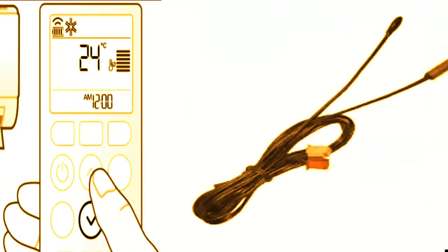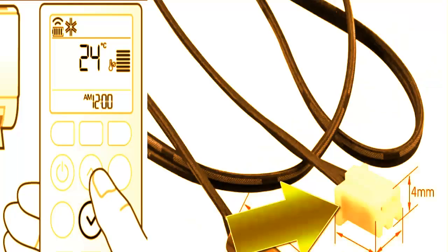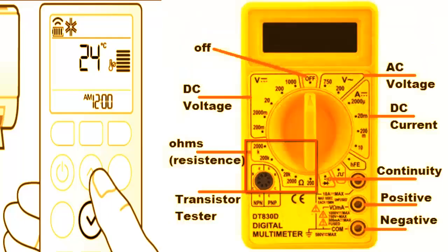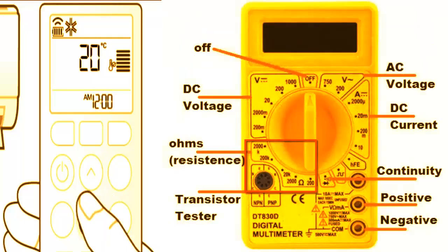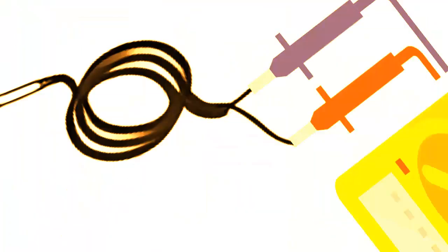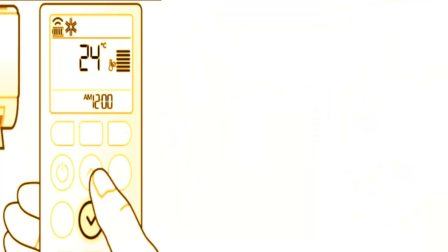4. Rule out moisture on the sensor and clean it with a dry cloth. 5. Also, check for potential false contacts between the sensor and the external electronic board, as well as the condition of the wiring. 6. Use a multimeter on the kilo scale to measure the electrical resistance of the sensor. The measurement should never be zero or infinite, otherwise, replace the sensor.